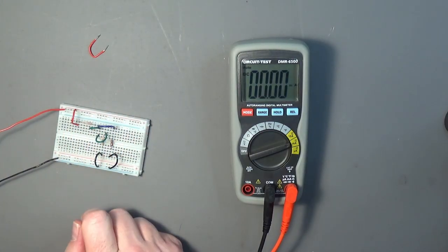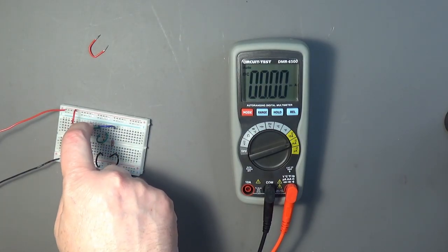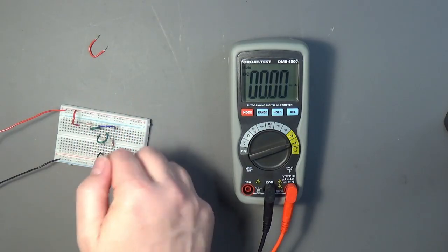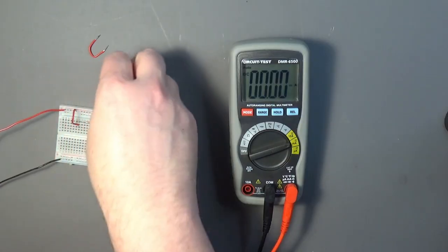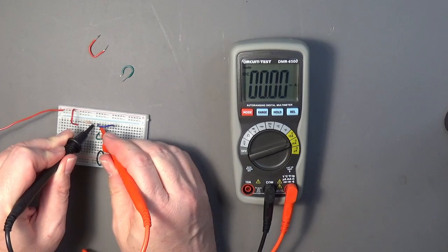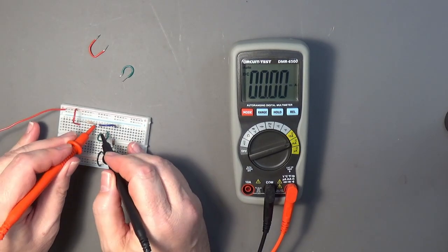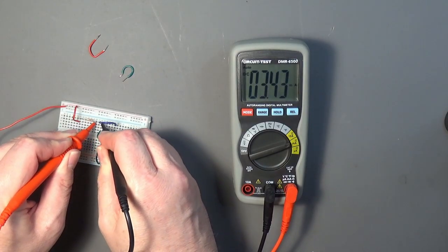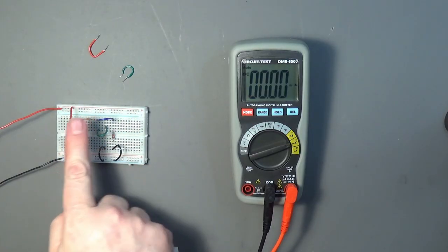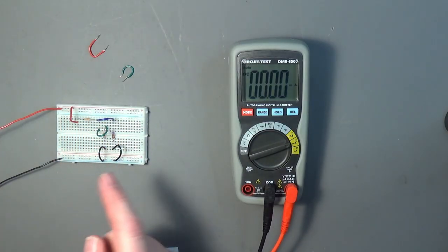Now I've got this hooked up a little funny, because then I can take this out and measure the current going between this and this parallel pair. If I were to just pull one of these out, I'd get just the current going through that one resistor. So I'm going to pull this out, and let's see what the current is going from our 1K resistor into our parallel set of resistors. Let's do that with the probe the right way around. And 3.43. So just like in a series circuit, this is acting as a series circuit. So these two parallels are acting like one resistor, and 3.43, 3.43, and 3.43.